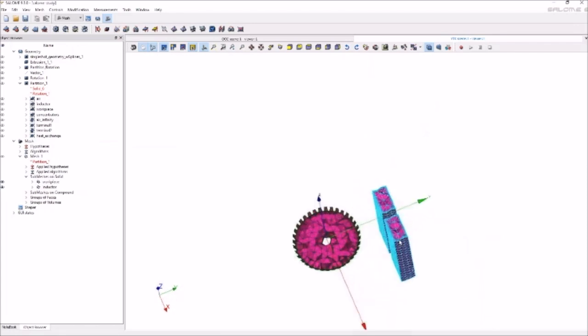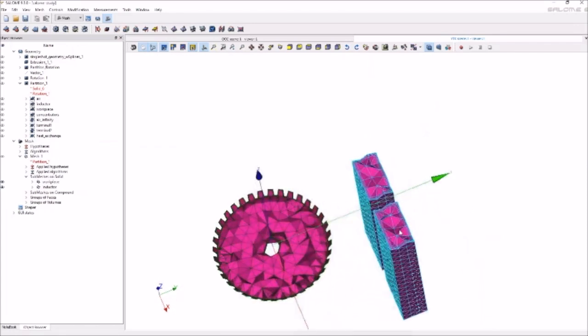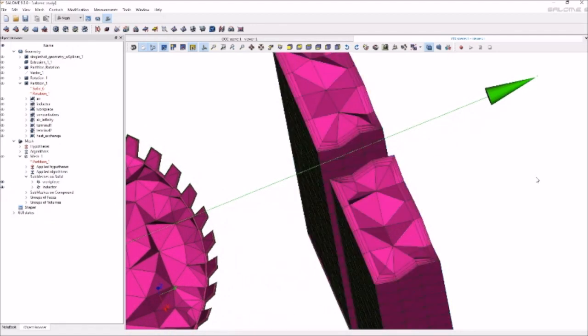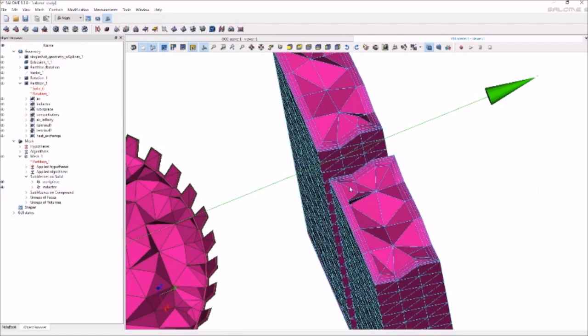And here I want to demonstrate a very useful thing. It's not common in simulation software, and that's why it really makes this software very good. I mean, you can see here what are called skin layers. So in the skin depth, we have to make the resolution careful. This specific tool allows us to make the layers.